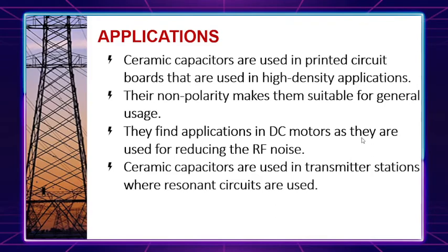What are the applications of ceramic capacitors? These components are used in printed circuit boards, which are high density applications. It's an unpolarized component, which makes it suitable for general applications. You can find this in DC motors, as they are used for reducing RF noise. When you say RF, this pertains to radio frequency. Ceramic capacitors are also used in transmitter stations where resonance circuits are used.